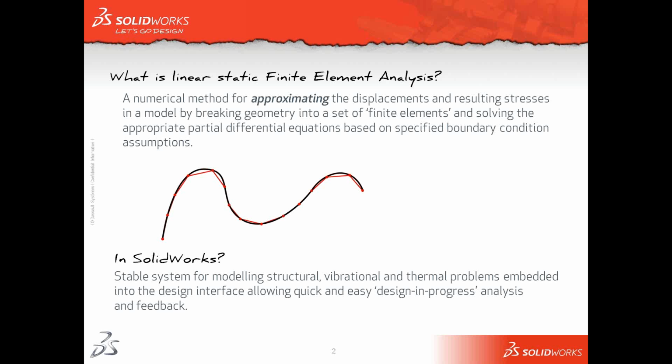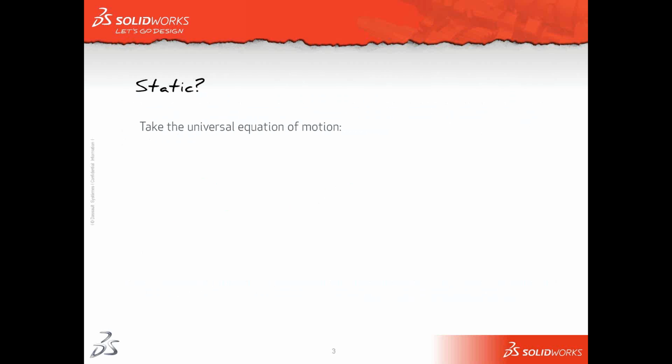So in SolidWorks, using the FEA finite element analysis tool, we can quickly swap between our design interface, which you'll all be familiar with, and our simulation analysis tool. This allows us to use the simulation tools not only to analyze whether our design is sufficient, but also to drive our design, because we can switch back and forth so easily.